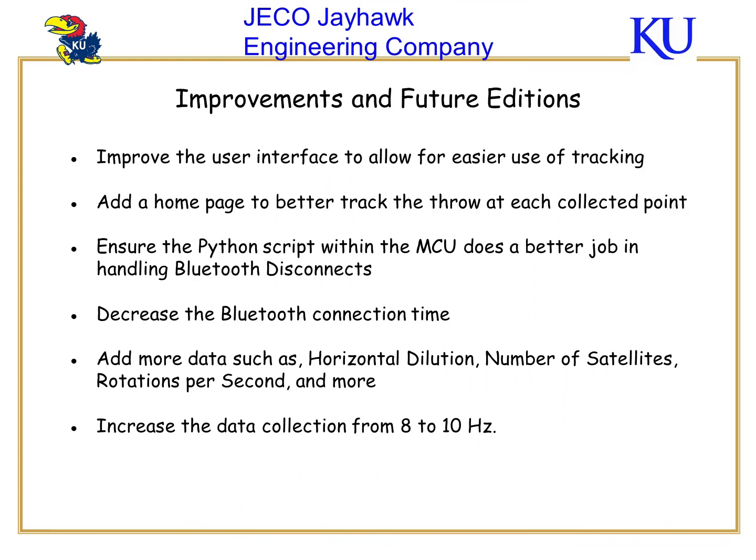Some future implementations we want to work on are to improve the user interface for easier use of tracking, adding a homepage to better track the throw at each collected point, ensuring the Python script within the MCU does a better job in handling Bluetooth disconnects, decreasing the time it takes to connect to the Bluetooth device, adding more data such as horizontal dilution, number of satellites, rotations per second, and more. Lastly, we want to increase the data collection from 8 to 10 Hz so that the application has more data to utilize.